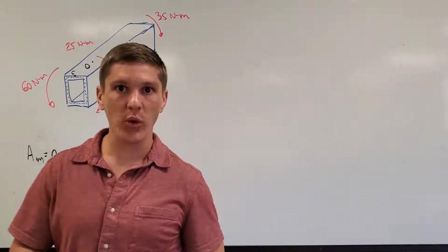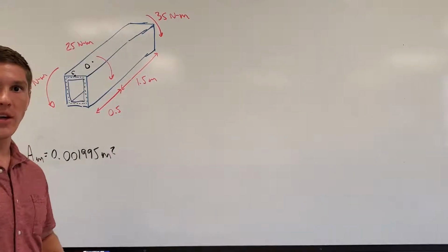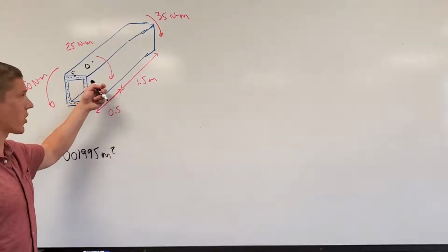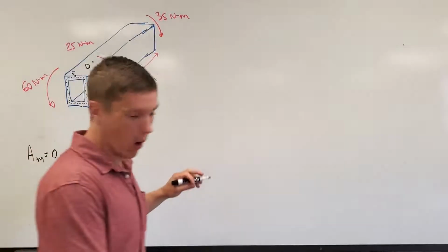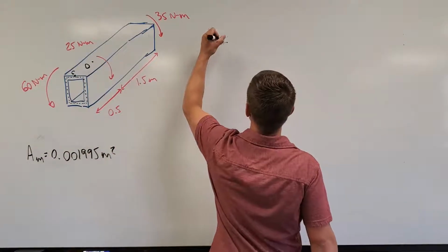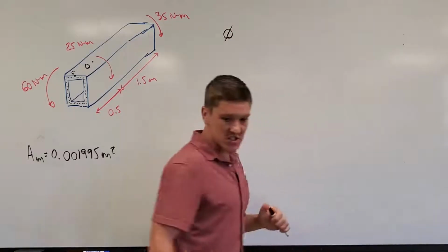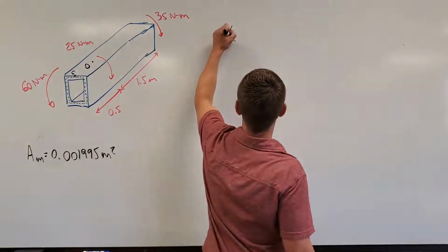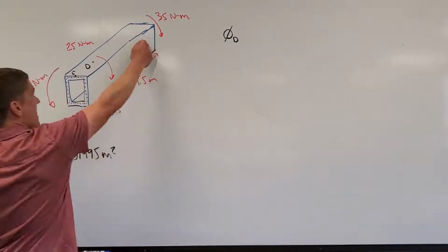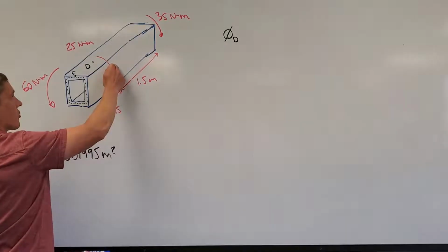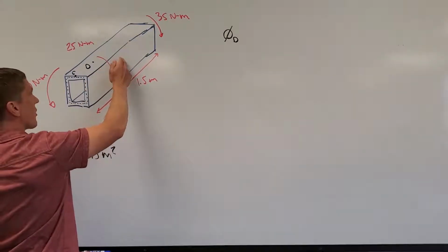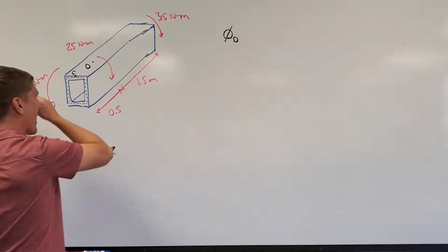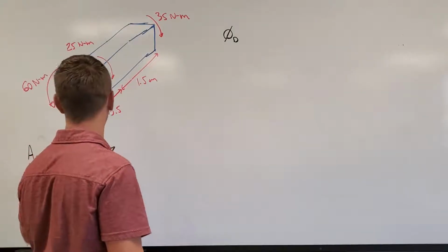So, that being the case, we need to take a look at what our equation was for rotation of a thin-walled shaft due to applied torque. We actually have to split this up into two problems. Our displacement angle is going to be at location D. We have a 35 Newton meter internal torque all the way to D. That 35 Newton meter internal torque is going to cause that free end to rotate by some amount.